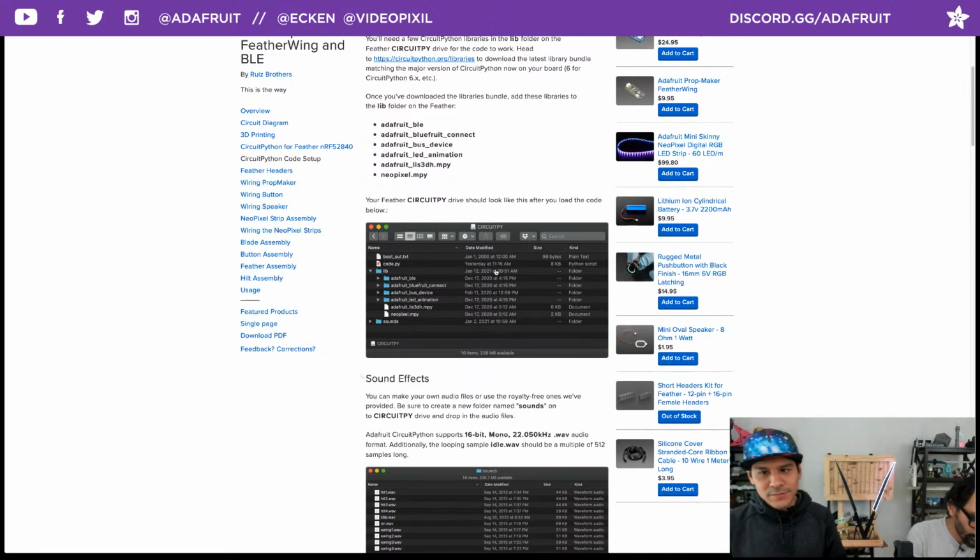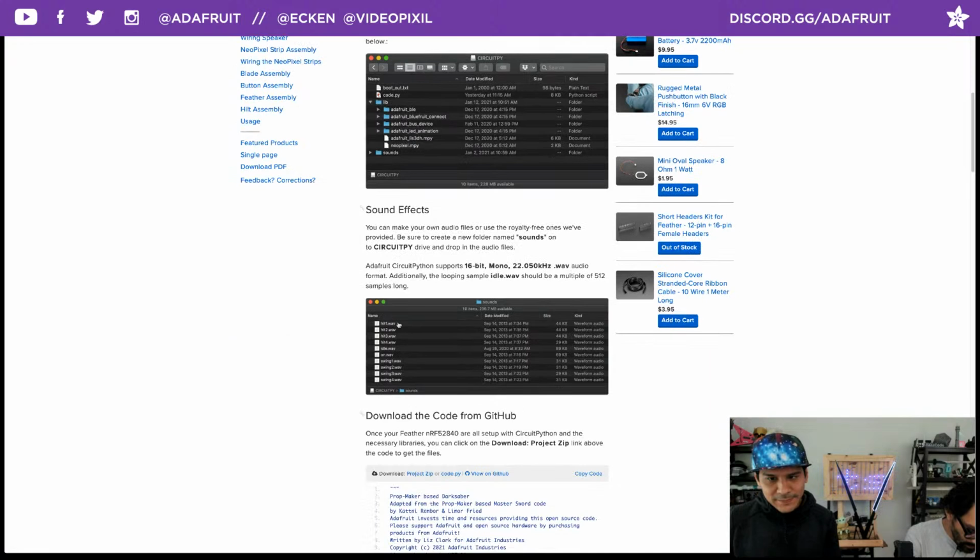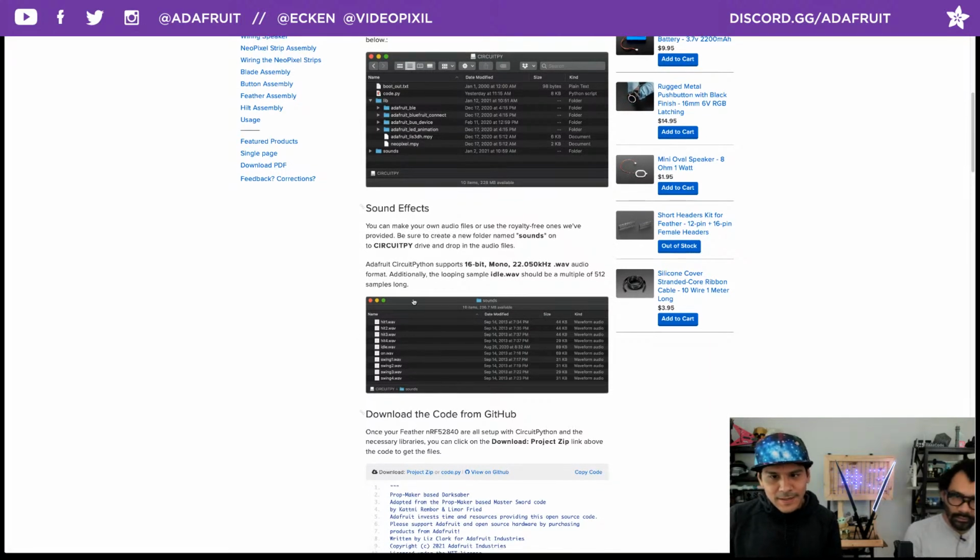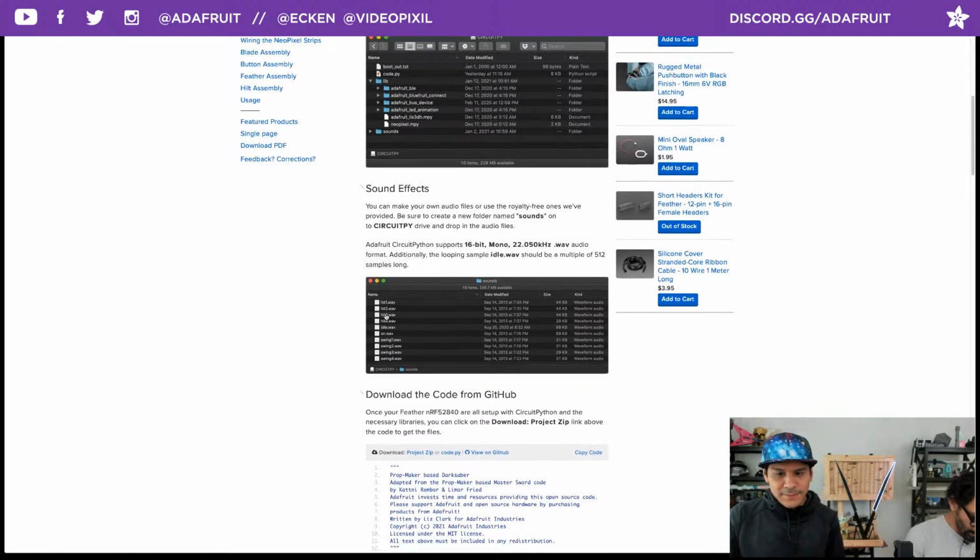So your CircuitPython drive. Whenever you install CircuitPython on any of the Adafruit boards, when you plug it into a computer, it shows up as a USB drive. Your code is there, your libraries, and your sound files, because this is, of course, a prop with sound. So next up, here's a list of all the sounds, the WAV files, and a little bit of note. CircuitPython supports the WAV format. It's 16-bit. If you want to create your own sounds, you want to use this information to convert your audio clips.